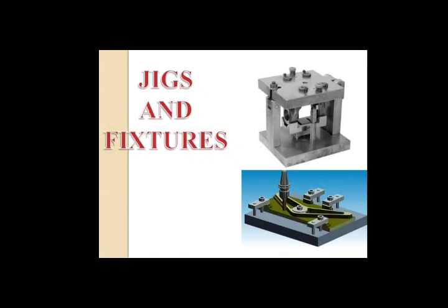Then, the information obtained from operation analysis is used to decide division of work, which includes determination of number of operations required, method of location, clamping, chip control, tool guides and positioning. If you go into the details, that includes locating, a determination of required locating points and locating surfaces to be used. Clamping requirement can be determined by studying the work cycle.